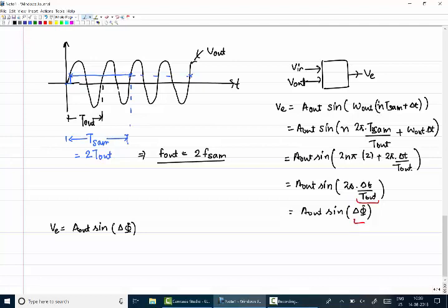You can even use this phase error detector when the frequencies are integer multiples, and you can lock for a zero phase error also. Such kinds of PLLs are normally called subsampled PLLs, where you use this kind of phase error detector.